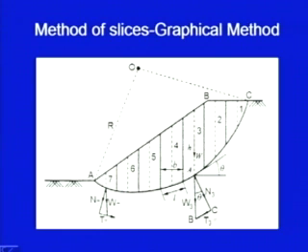So, this angle will be 90 degrees, draw a line at 90 degrees and get the intersection point C. So, you will be getting N3, T3, and this angle will be, let us say, theta. So, you can get the N component, you can get the T component. Same thing is here, join it with the center, extend it, but the direction of T now in this case is opposite. And this W7 represents the weight of this slice.